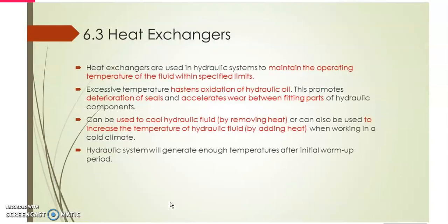Okay, so next, the last subtopic, heat exchangers. The purpose of heat exchangers is to maintain the operating temperature of the fluid within specific limits. Why do we need to maintain the operating temperature? This is because excessive temperature hastens the oxidation of the hydraulic oil, and this will promote the deterioration of seals and accelerate wear between the fitting parts of the hydraulic components.